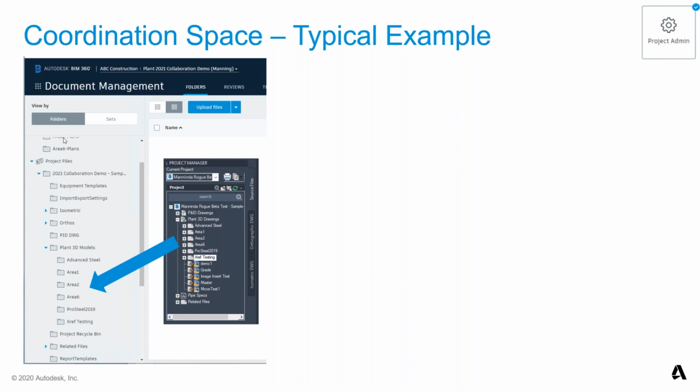Also, what you can do directly while viewing the clashes is create issues. So you could directly create a task that you assign to someone from the project, where you say, okay, you please will be the one to avoid this clash by taking action.